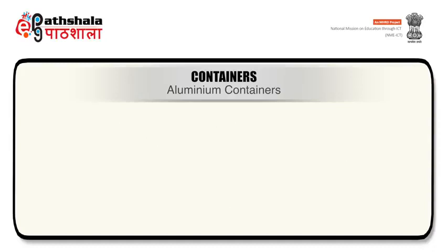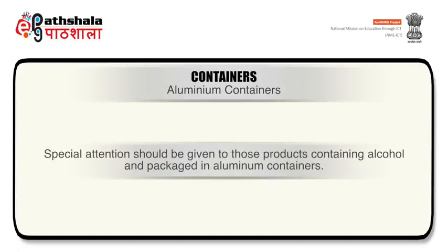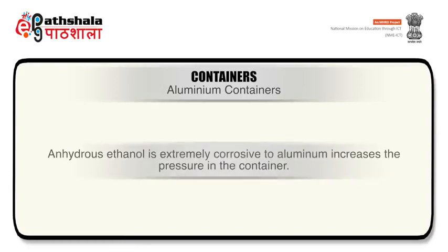Now the aluminum containers. Aluminum containers are seamless, resistant to corrosion and exhibit lesser incompatibility problems. Special attention should be given to those products containing alcohol and packaged in aluminum containers. Anhydrous ethanol is extremely corrosive to aluminum and increases the pressure in the container.